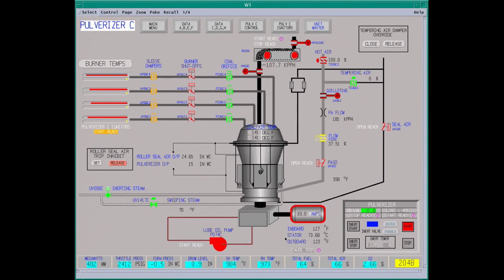These are Foster Wheeler MBF pulverizers. They're a roller type. I mean, there's different types of pulverizers out there. We have 2 of the older style that had the planetary rollers with springs on them, the MB, and then 6 of the lower ones are the MBF, which the rollers are stationary and the table moves. These are a lot more durable. They can take a lot more. They're not as sensitive as the other ones are, the older style.